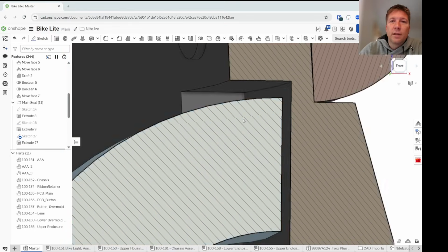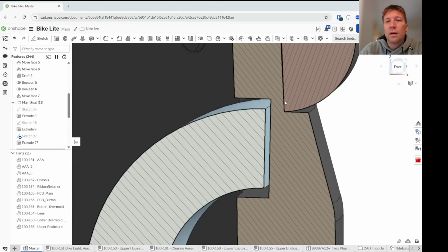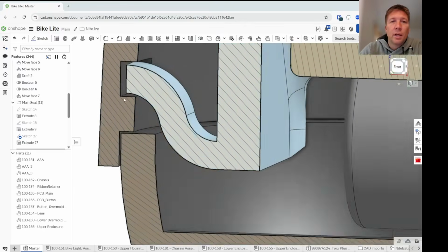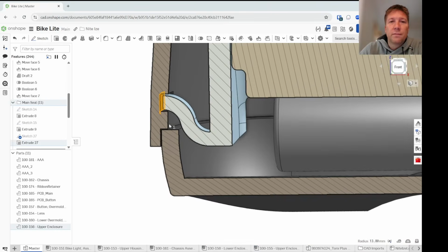Now this is a very thin wall right here. This may be an area of concern for manufacturing or for mold filling. So this would be something I would want to carefully understand and look at before we ever release parts for manufacturing. But over here, a local thin spot on this big of a body would be just fine.